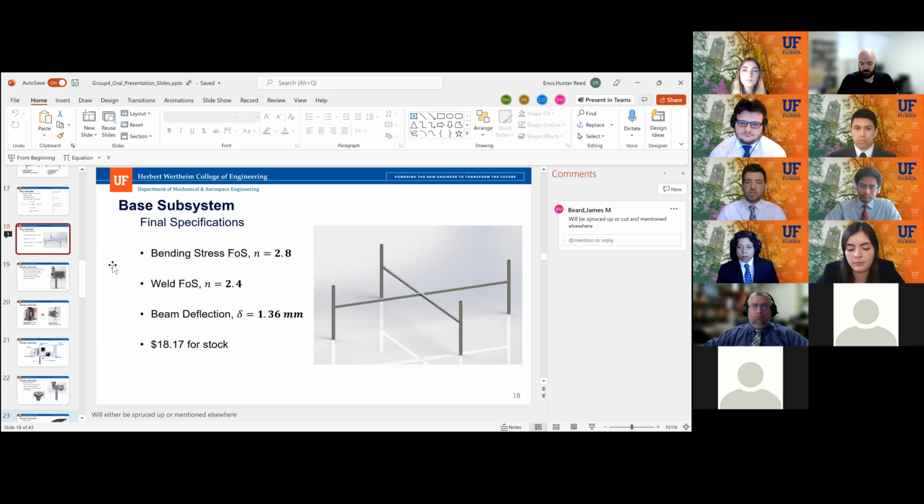And you have an entire rigid structure that keeps it from shifting or leaning because of, not to say lack of depth, but lack of depth as far as how far normally a pole like this would have to be cemented if it was standalone. And so if it was a big concern, you could put a little, like a pot-sized amount of concrete at the bottom if it became a big concern, or in testing it came out to be, but it would be a dramatic decrease in having an entire concrete pad. But we don't assume that to be an issue.